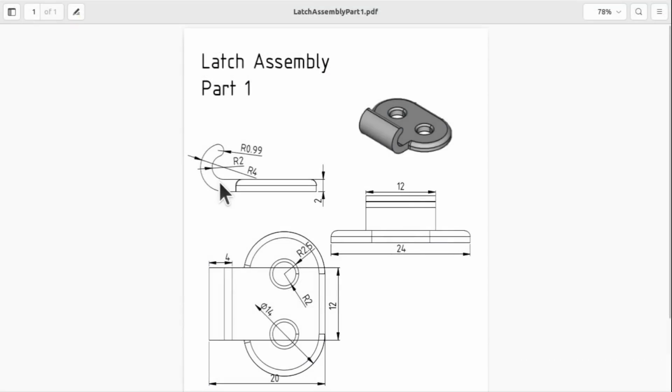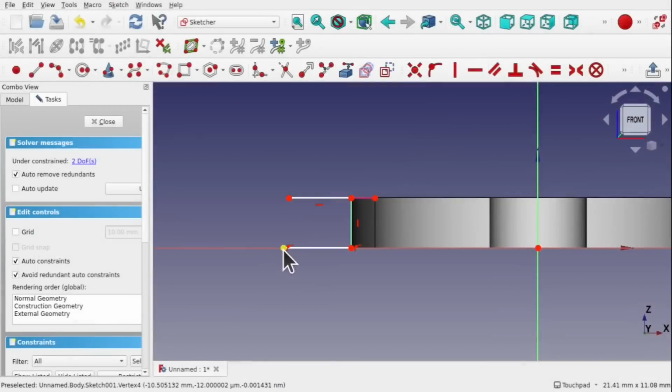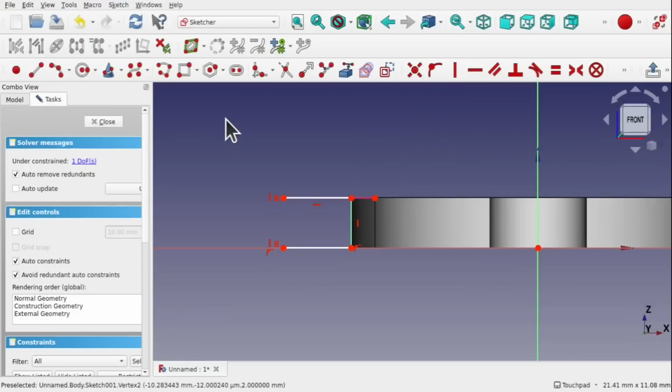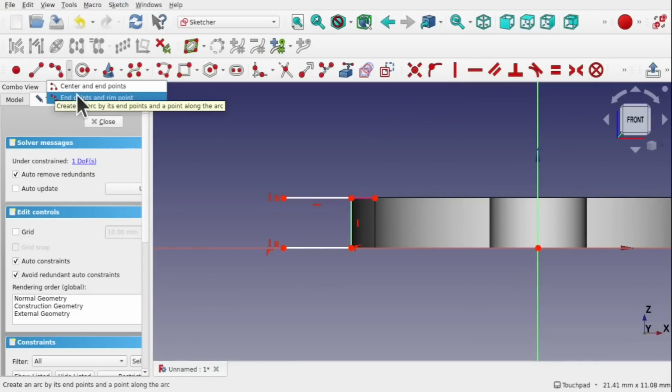Looking at the arcs, we can see that these lines where the arcs start basically attach to these lines, and these points are in line. Follow this up, we can see that the arc comes around and it's basically in line with those points as well. We've got no length here, so that's going to be derived by another measurement elsewhere in this diagram. So let's take these 2 points and place them in line, vertical constraint,